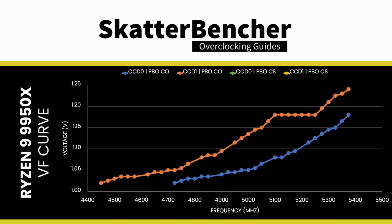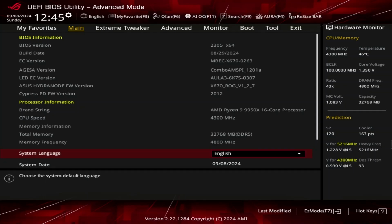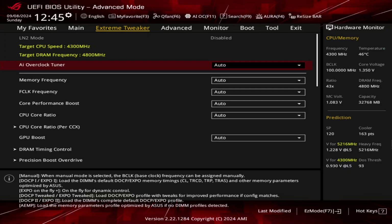In the second graph, we compare the curves using the Y-Cruncher BKT workload. This workload is relatively light as it doesn't push the CPU to its TJ max. However, the operating temperature is around 80 degrees Celsius. We can see pretty much the same. So the key takeaway is that with the high temperature curve shaper, we're getting more undervolt at the hotter parts of the VF curve.